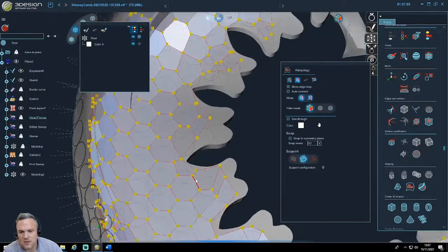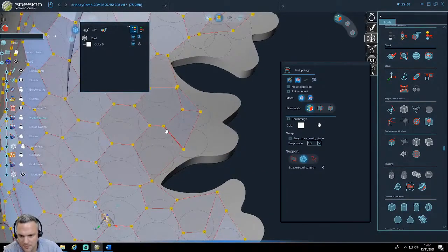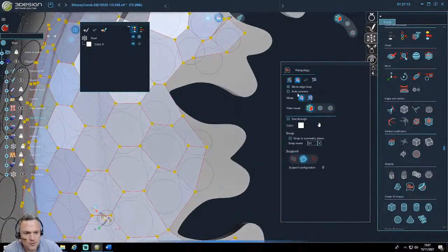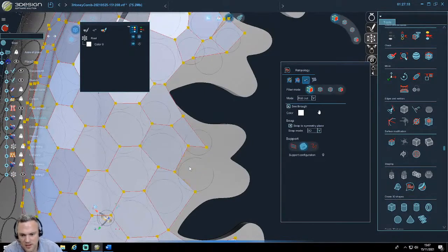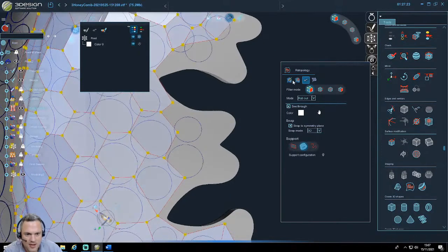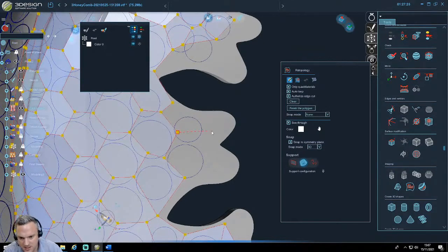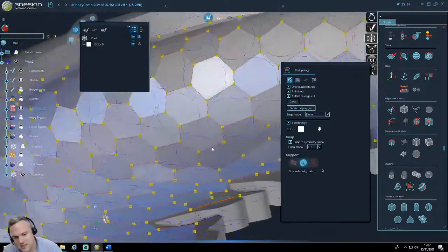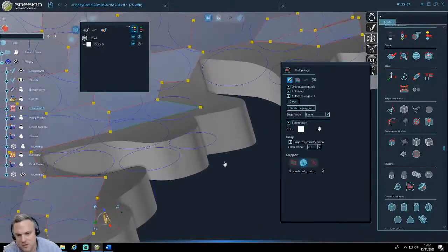So as I said, you can modify the position of the points like that. Or if you want, you can also remove. If you are not happy with this shape, you can remove that one and also that one. And I can create mine by clicking. It's really easy to do. I just have to select the connection for the first points, and I click on the surface, and automatically the surface will be created on the support, which is my object in gray.